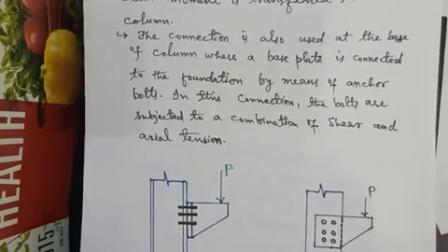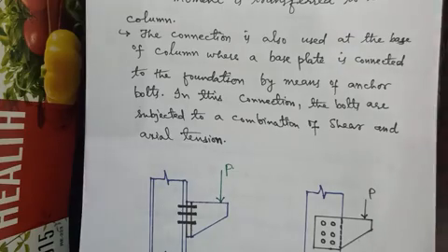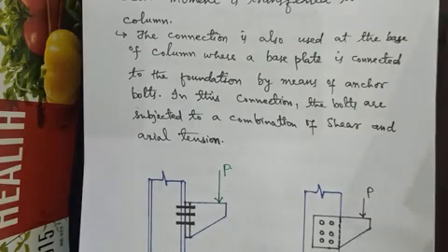So the connection is also used at the base of a column, where a base plate is connected to the foundation by means of an anchor bolt. In this connection, the bolts are subjected to a combination of shear and axial tension.